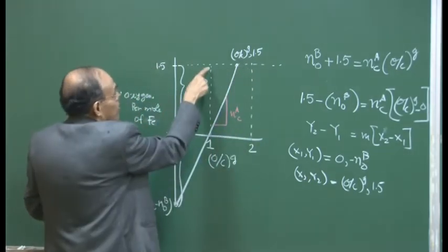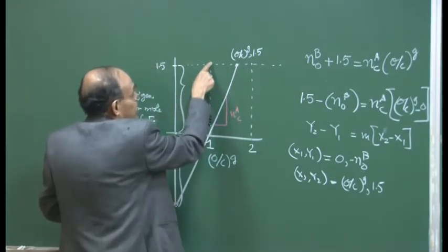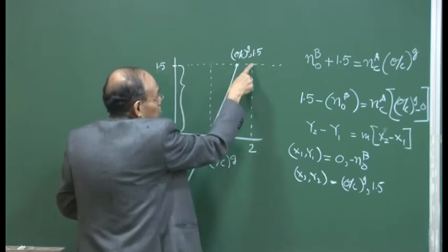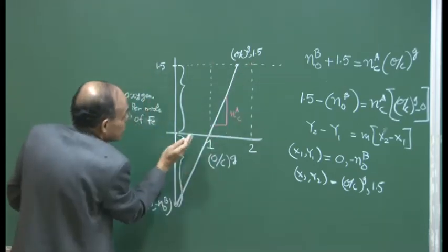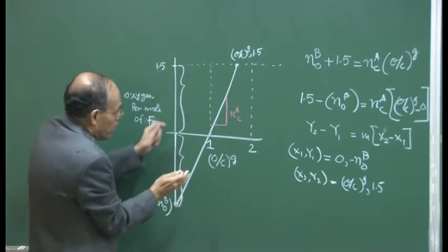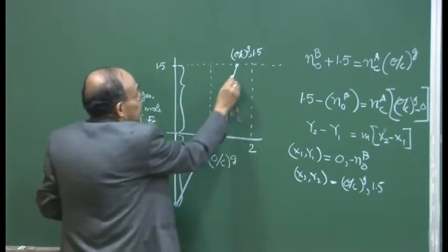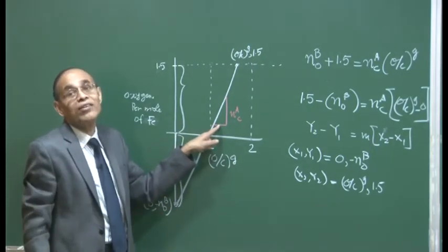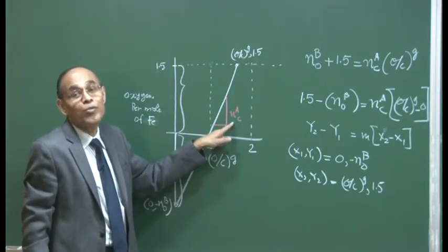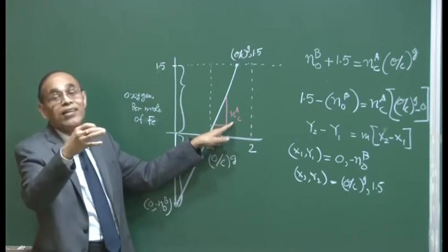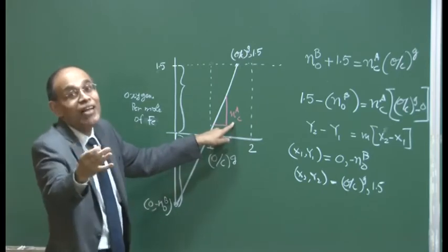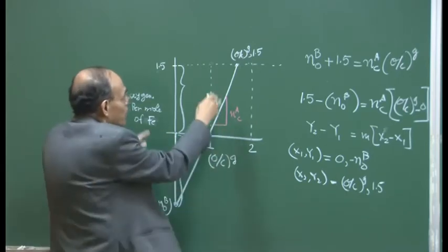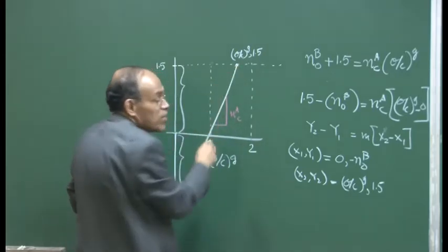This 1 essentially means O by C is equal to 1, the 100% CO point, and this is the 100% CO2 point. So, as the slope becomes less steep, you have more carbon dioxide, and the coke rate is going to decrease, which shows that the furnace is operating at a higher efficiency, because the coke rate is small and the gas contains more carbon dioxide.